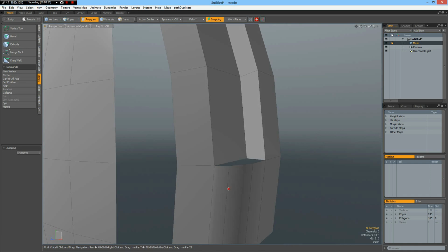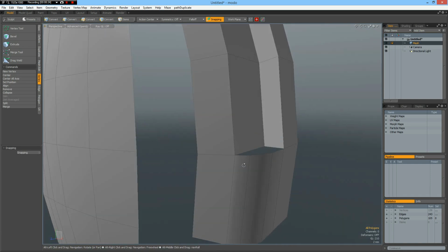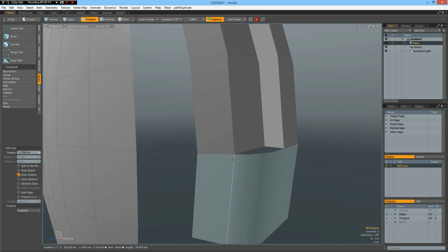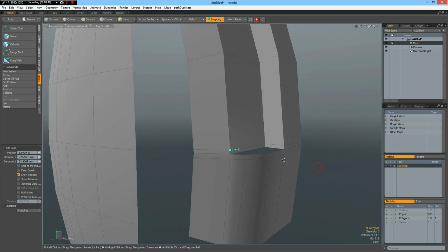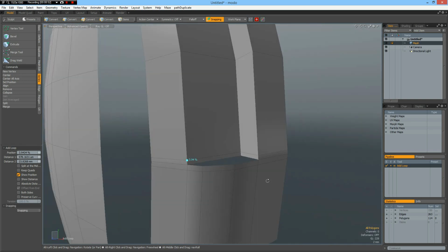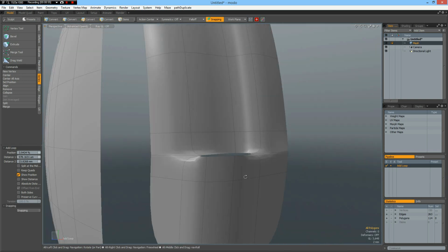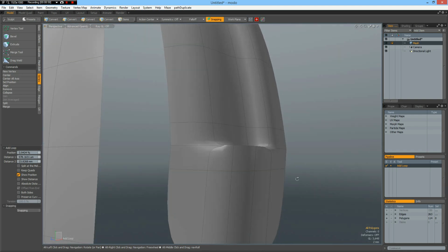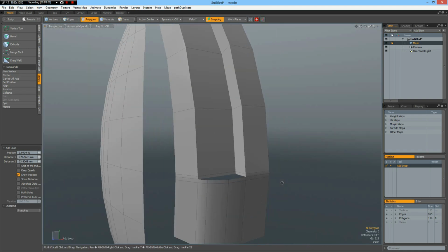So you will see what I mean. So if you remember my how to avoid spiders tutorial, then you know we need to make squares around here so we can get rid of one of the edges, or two of the edges rather. So I start with putting a single edge in here and a single edge in here, and already we have the first problem. If I would leave this here, this is like hardening an edge, and you would see it when we render it. So this is what we must get rid of first.